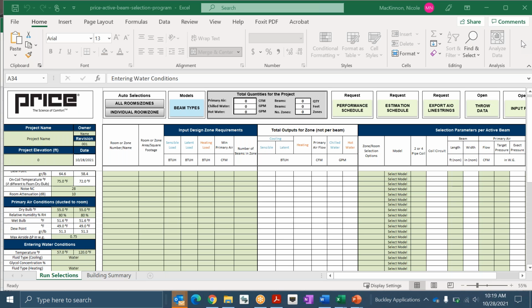When you drop below 0.2, it's roughly 1,200 feet per minute at the nozzle. That 1,200 feet at the nozzle is a point where we can't really accurately measure the induction rate. So a good rule of thumb is don't go below 0.2, because we really can't be too accurate there. I also wouldn't go any higher than 0.75 unless you're making an individual selection.